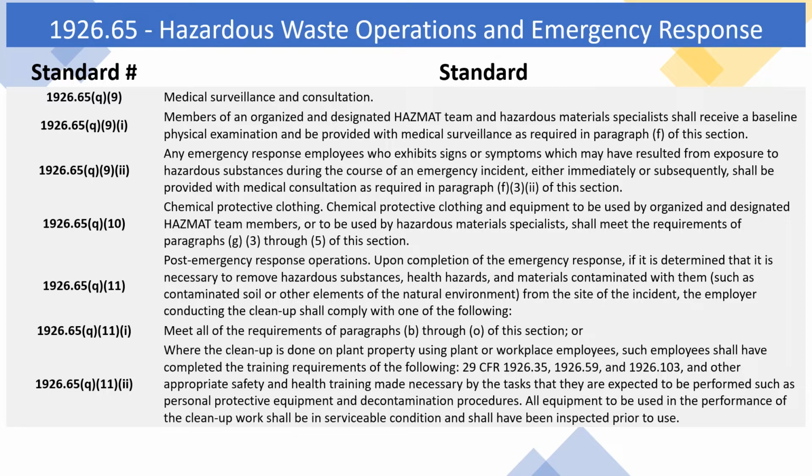1926.65 Q11 1: Meet all of the requirements of paragraphs B through O of this section, or 2: Where the cleanup is done on plant property using plant or workplace employees, such employees shall have completed the training requirements of the following: 29 CFR 1926.35, 1926.59, and 1926.103, and other appropriate safety and health training made necessary by the tasks that they are expected to perform, such as personal protective equipment and decontamination procedures. All equipment to be used in the performance of the cleanup work shall be in serviceable condition and shall have been inspected prior to use.